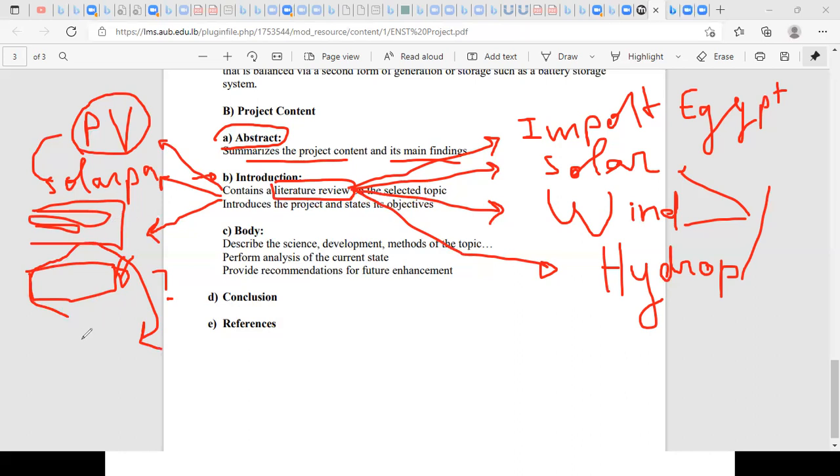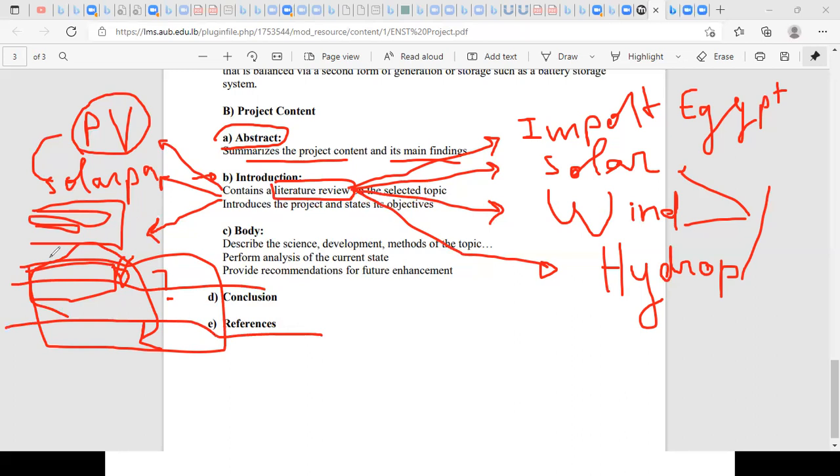So this system, if combined, let's say, with any heat exchanger, in which you have a flow of water or a flow of refrigerant, this energy that is extracted from the surface to keep it in the corresponding limit can be used for other purposes, can be used for heating applications. So this is what we call heat recovery. One of the main strategies to increase efficiencies is to use the heat recovery concept. So this is an example of ideas you can use. You have a lot of possible ideas you can take.